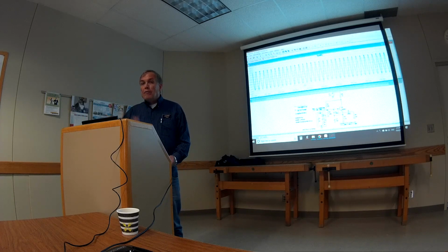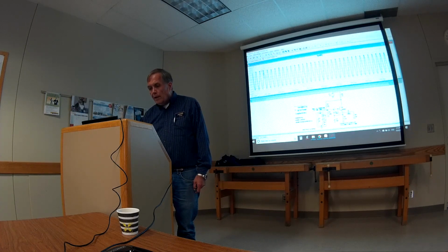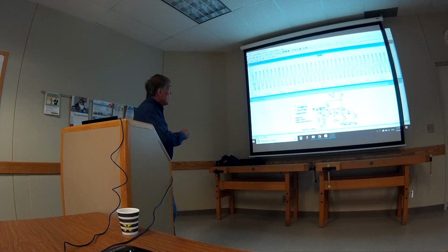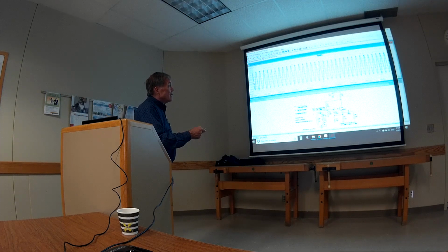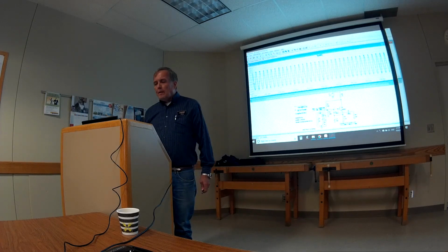Now, you want to ask, what frequency is it running at? This is the next slide, but I'm doing well in here. There are a couple of ways of doing this. One thing, you could start over to the left and ask, what's the time here? Okay, 891 microseconds. What is it over here? 896. And you can count the number of pulses and divide it by the time that elapsed. Then you'll have the frequency.